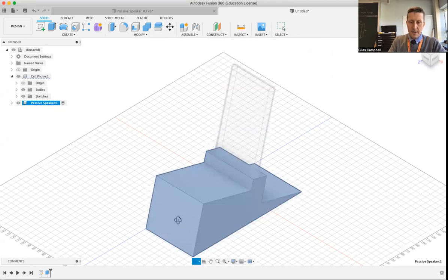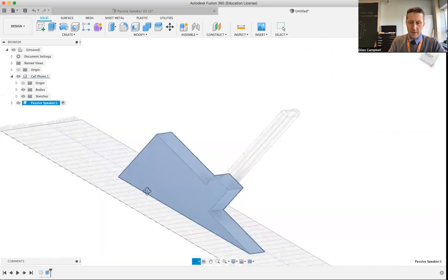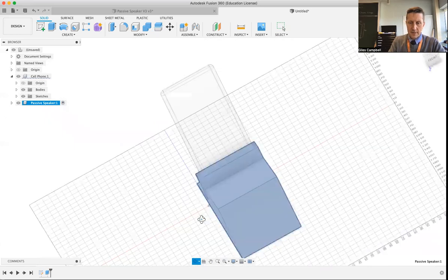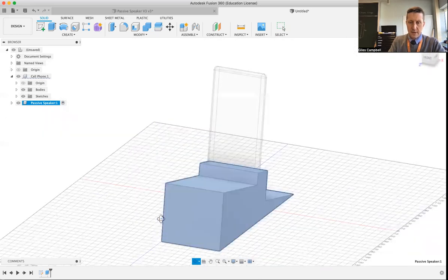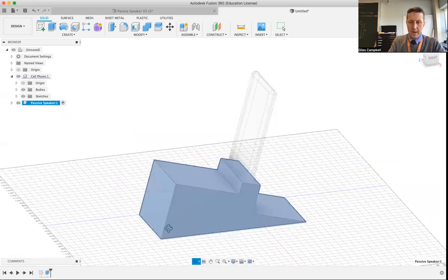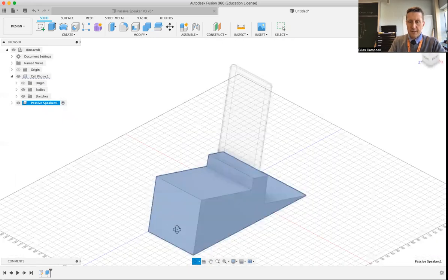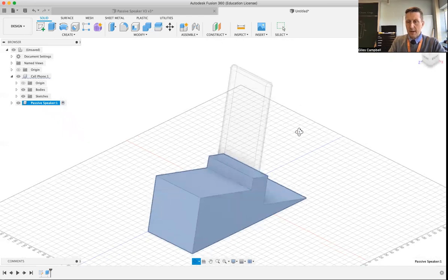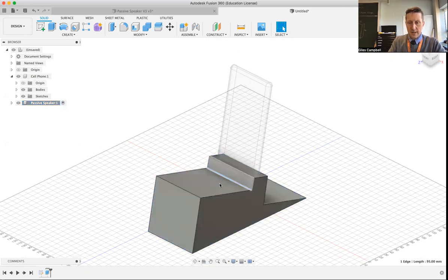If we want to, at any point, we can have a look at how it looks. So I'm pretty happy with that shape. I just need to now start working on some radius and filleted corners. So I'm going to come out of this orbit tool by clicking far away. So one of the things I want to do is round this angle here.